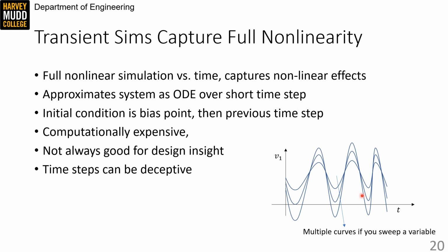Finally, beware of the time step setting on transient simulations. Making it too short will cause your simulation to run for a really long time, but letting it get too large can hide oscillations or other behaviors in your circuit. The time step will automatically adapt in SPICE simulators, but you have some control over it, and you should use that control to keep an eye out for suspicious simulation behaviors. So the time step can hide stuff or let your simulator lie to you in one way or another.